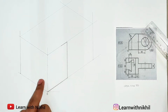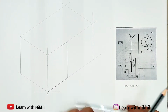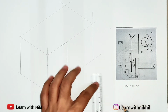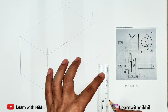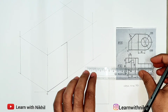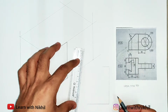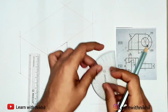So first we have to plot this part two-dimensionally. So I am drawing here separately the two-dimensional view. We have to find the height. So this distance is 50. We are plotting this two-dimensionally on the side so we can find out the height. Height is 70. This distance is 15. Now here we can plot the angle. We can't plot the angle in three-dimensional, we have to do it in two-dimensional.